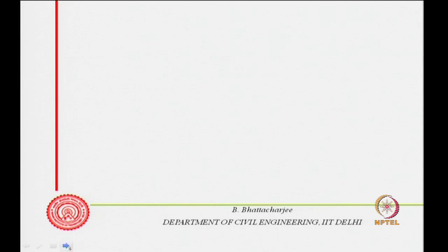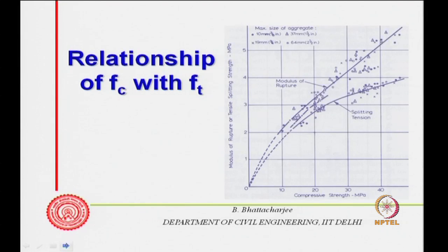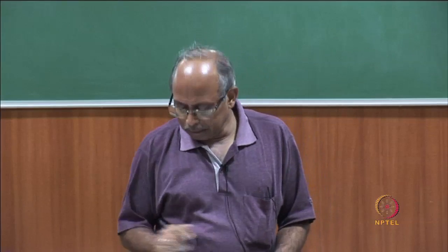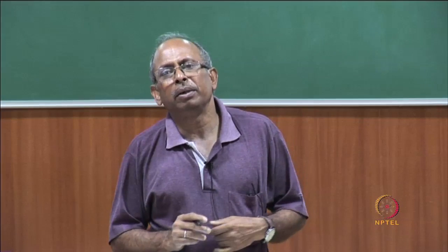And similarly, if you measure by split tension, you get something like this. This is the flexural test, we will talk about that sometime later. So, generally with various sizes of aggregate, you can see typically it will vary in this manner, some sort of variation is available, and people have tried to empirically relate the tensile strength, this is split, this is flexure, to the compressive strength.